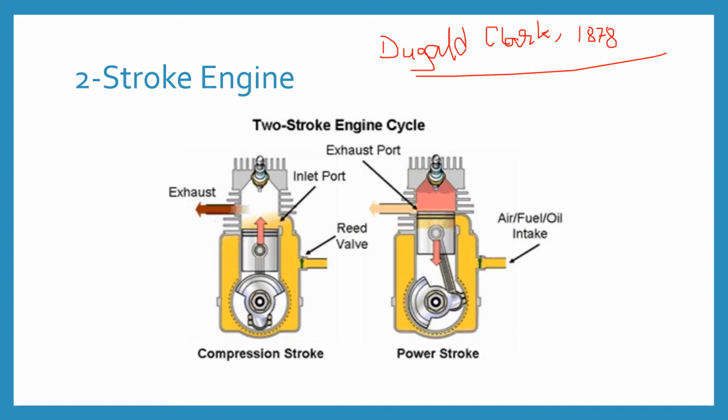The induction of the compressed charge moves out the products of combustion through the exhaust port. Therefore, no separate piston strokes are required for these two operations.